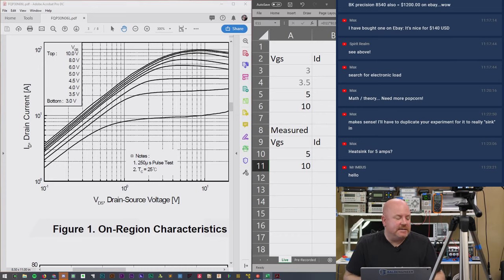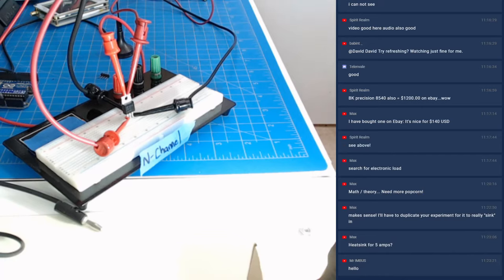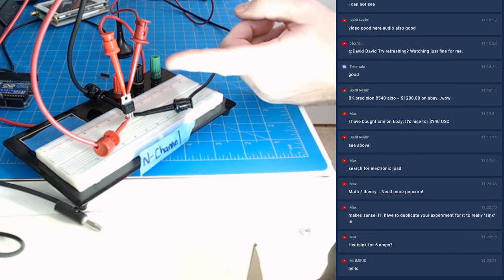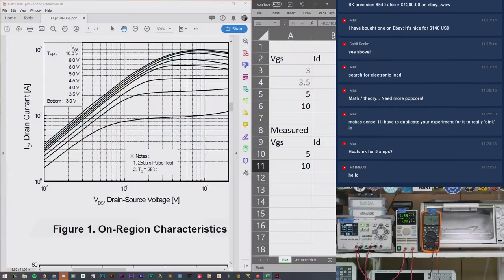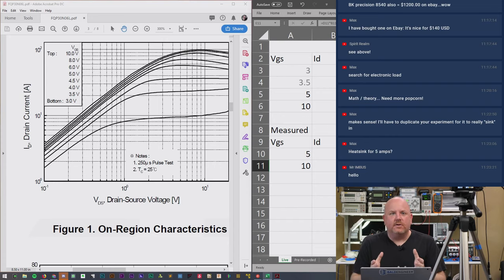Now, since this is a TO220 package, the traditional larger transistor style package, it can handle something on the order of about 2.4 watts before you absolutely have to have a heatsink. So this is actually going to work out well, because this basically says with either of these at 5 amps, we don't need a heatsink.